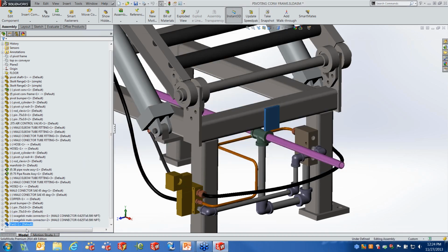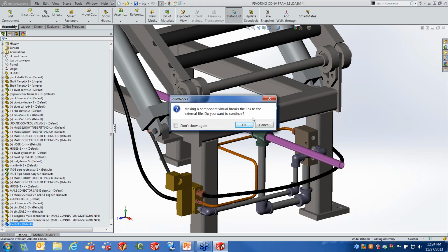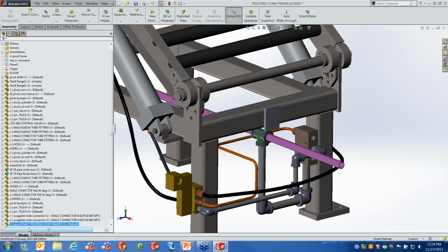And once you say OK, the set of brackets now gets removed, and the name that I give it in the save as becomes traditional like we're used to. You're also going to have the ability in SOLIDWORKS to make components that are saved on the hard drive virtual. So now this thing exists on my desktop. I want to virtualize it and embed it in this assembly. It's always going to tell you it's going to break the link to the external file, and now that set of brackets gets in there to let me know that it's virtual.